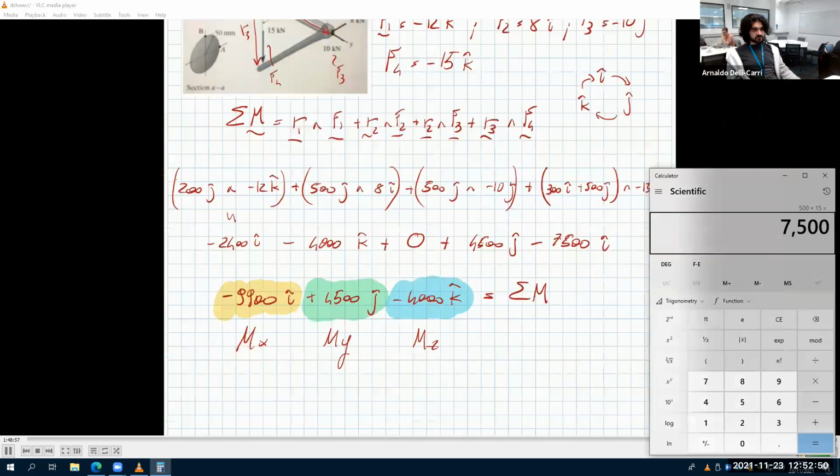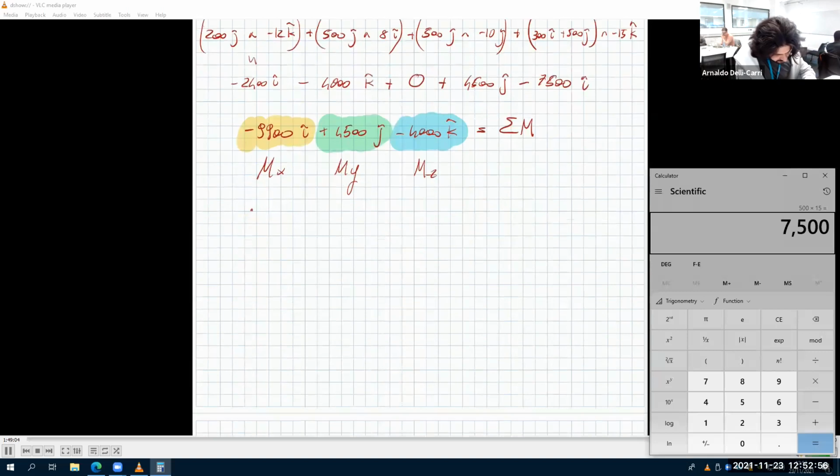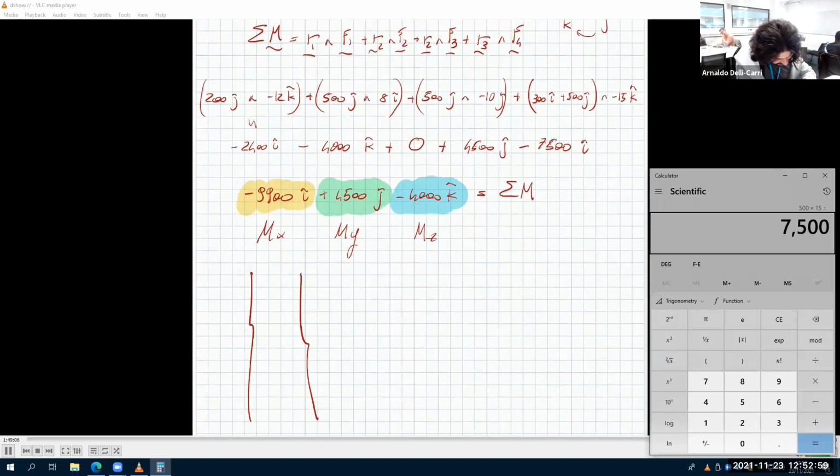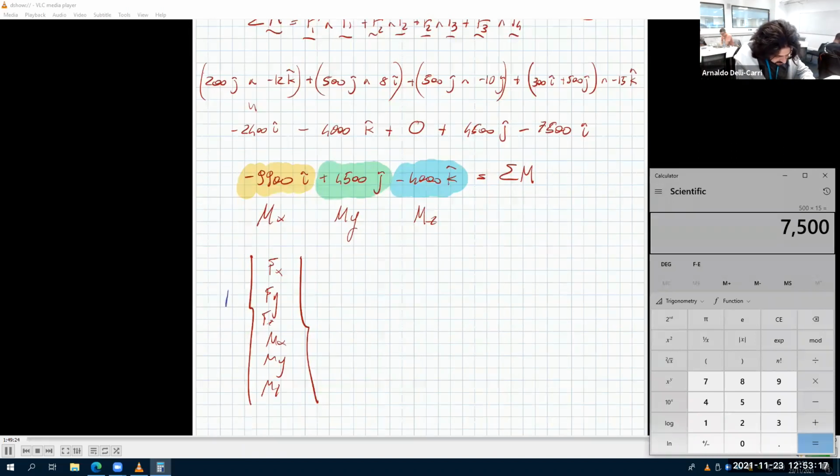We just have to find out which one is torsion, so let me do that as my last step. We have Fx, Fy, Fz, Mx, My, Mz. Some of them are torsion. So this is the section we are interested in, and the y-axis is normal. So Fy is the normal force, and that means My is the twisting load. Everything else is a shear force, Vx, Vz.